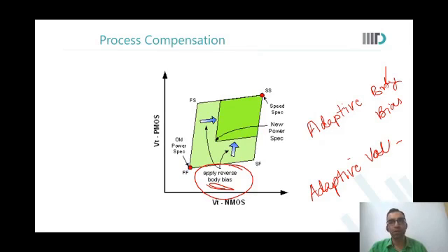Okay. Raghav? So the body bias was applied for the fast and the voltage for the slow. So kind of. I could apply voltage for fast also. I could lower the voltage and reduce the overall power consumption. Okay, right. Both these techniques are available for the corners. Yeah. So by using these techniques, I'm trying to basically move the devices towards a typical corner. I'm trying to bring the device back into my specification for, say, let us say leakage or power consumption or timing or whatever.